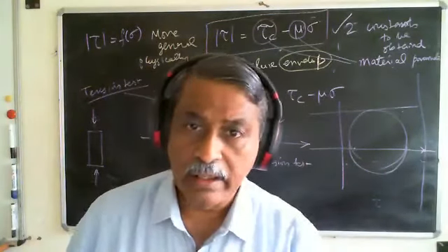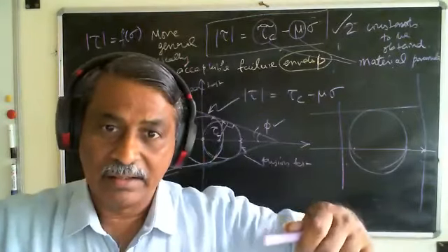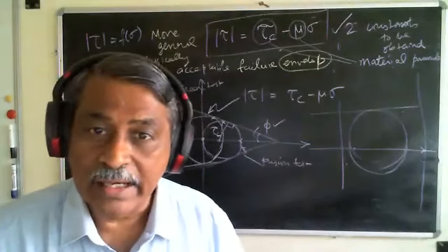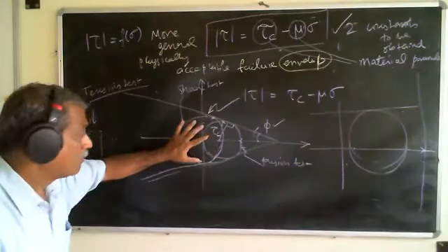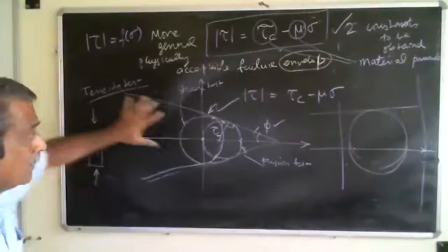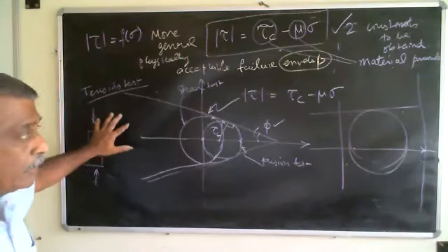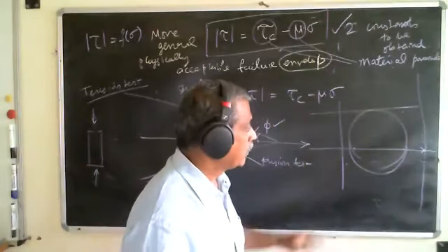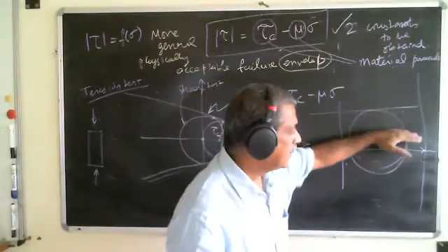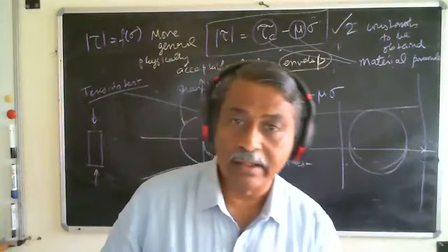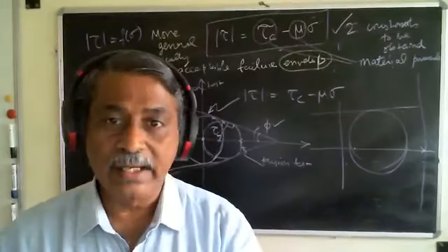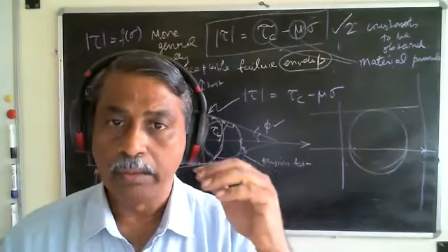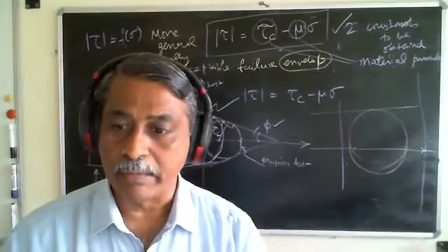Mind you, for brittle material alone, it is only the tension that is responsible. So if I do a compression test, I will not get anything that is meaningful, because the compression test will give me a circle which is the compression side of sigma. I need to have some tension side that is available as far as the circle is concerned. Based on that, I'll be able to evaluate whether the material has failed or not. So a stress state that will give me a failure mode is what I should have in the experiment.